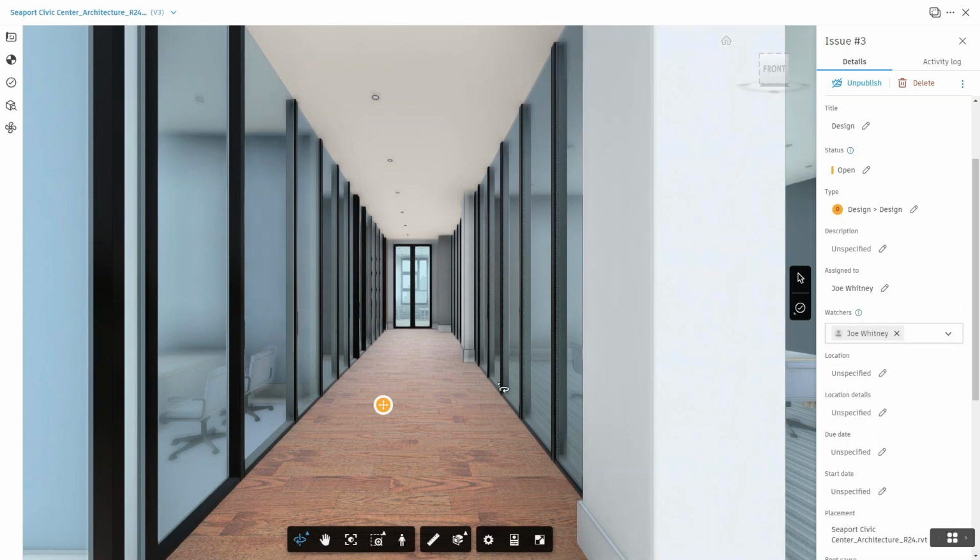these issue and data nodes actually go back into Revit. So there is a plugin within your design software of Revit and AutoCAD that you can use to track these in real time and change the status and manipulate them while you're working on the project. So if you're doing a QA/QC of the actual Revit model or CAD file, you can go through, do all your markups, and the designer in those design softwares can go through and track all those and, one by one, take care of all those issue nodes.